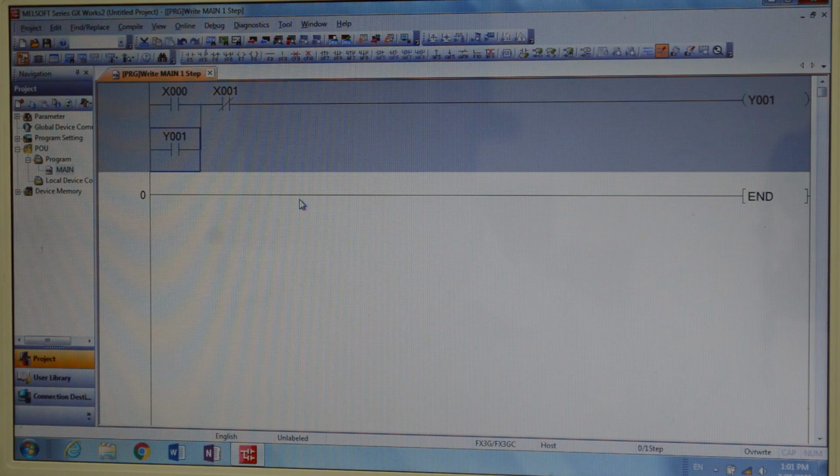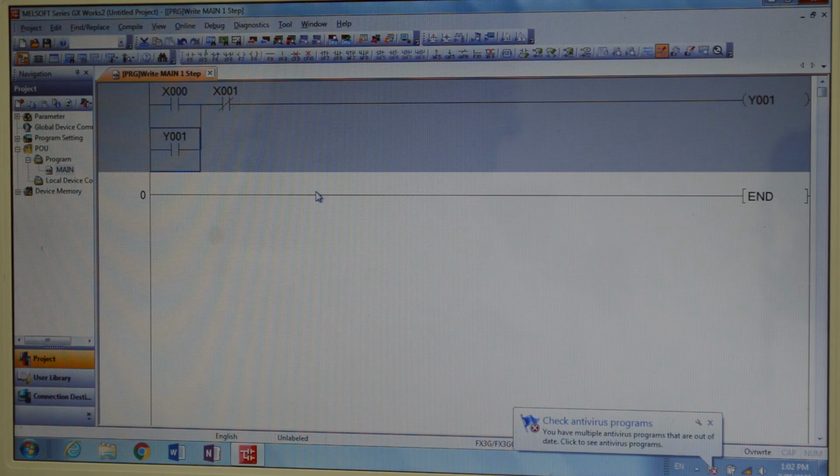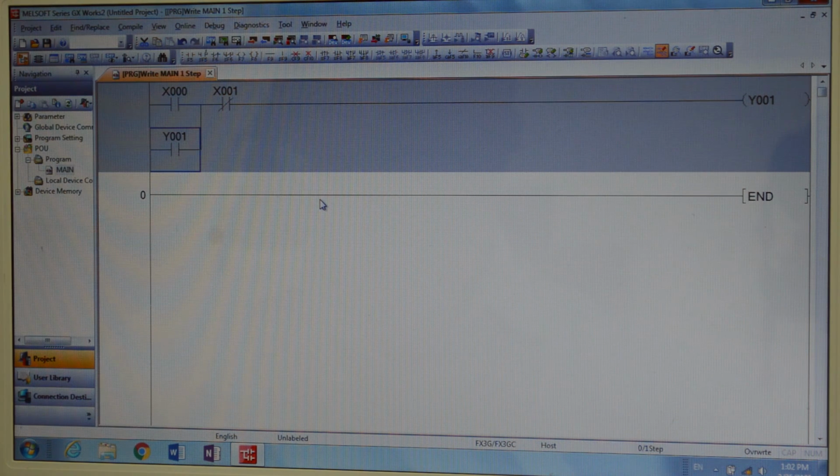The only difference is that the assigned numbers of the inputs or the outputs are different. Similar inputs can be used as long as they operate at the same time, regardless of whether normally open or normally closed contact. But two similar outputs with the same assigned number will appear void or not valid. So you need to assign a new number.